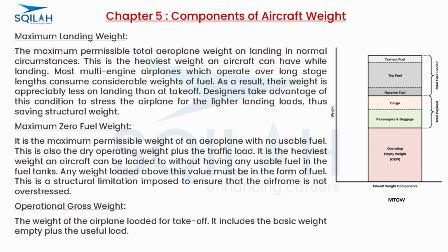Maximum zero fuel weight. It is the maximum permissible weight of an airplane with no usable fuel. This is also the dry operating weight plus the traffic load. It is the heaviest weight an aircraft can be loaded to without having any usable fuel in the fuel tanks. Any weight loaded above this value must be in the form of fuel. This is a structural limitation imposed to ensure that the airframe is not overstressed.